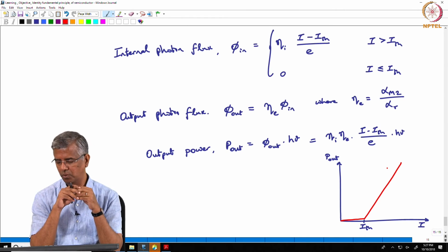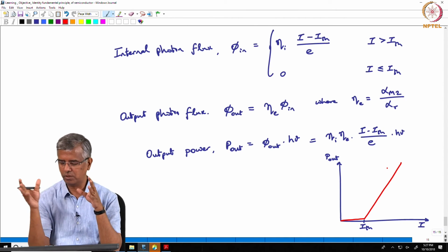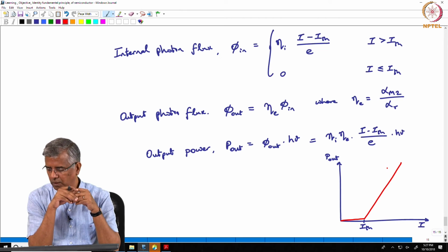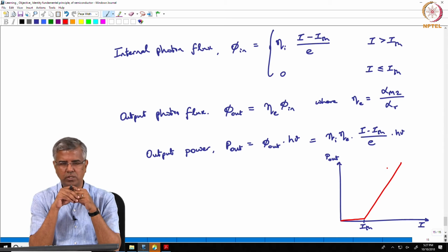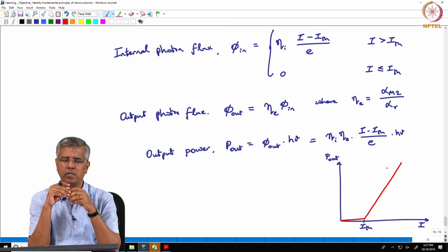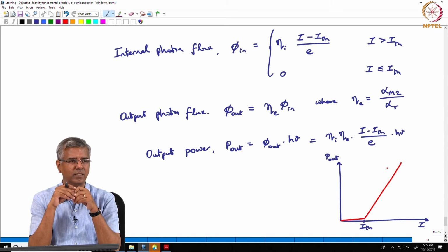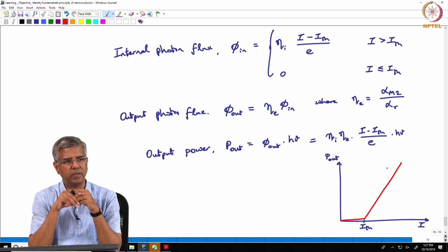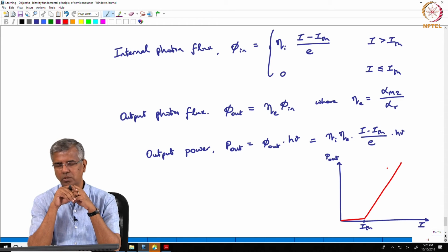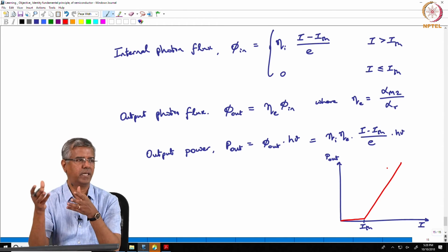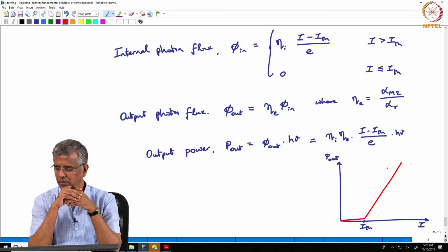Okay, and then of course you go on to using 800 nanometer laser diodes, 980 nanometer laser diodes. Where is 980 useful? Pump diodes for your amplifiers. We saw with your erbium, or even ytterbium, also has gain around 980 nanometers. So you can use these lasers to pump other lasers.